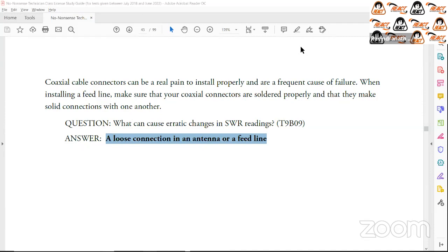You can use good quality coaxial cable that is UV rated, intended for use in ultraviolet environments. Sometimes you may have a marine environment as well, so you need to use cable that is suitably manufactured for UV. Also, at the ends where you have the coax cable and the connector, you may want to apply sealant that will also protect the ends from fraying out as well, right? Appropriate coax seal will work just fine at the ends.